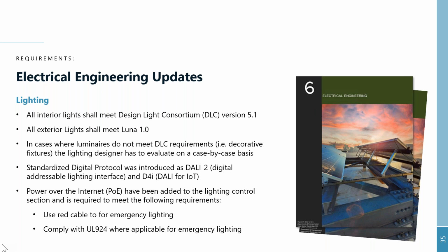The new 2024 standard uses the digital protocol DALI 2, Digital Addressable Lighting Interface, and they introduced the Digital Addressable Lighting Interface for IoT, which they call D4i, because of the introduction of Power over Ethernet that is coming on the market, and GSA wants to use it on some of the projects.